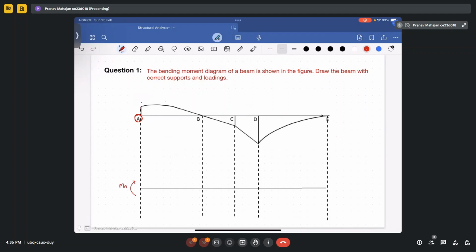Okay, at that point A. So now see, this is your 2D profile, 2 degree curve, and in the first week we have seen that the UDL will be having the 2D curve along its whole length for the bending moment diagram, because its equation is coming out to be WH square upon 2. Okay, this is for the UDL case.